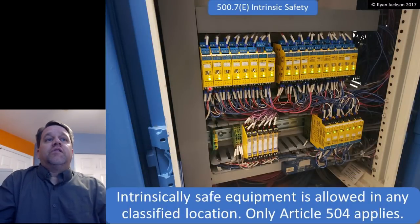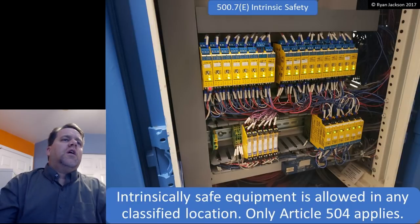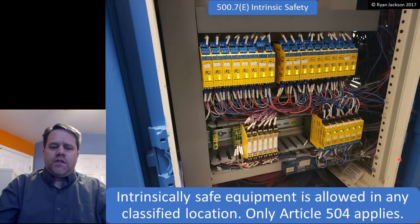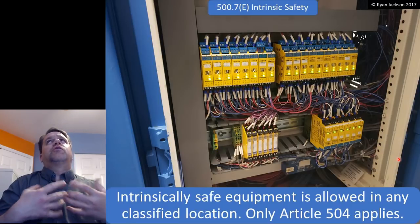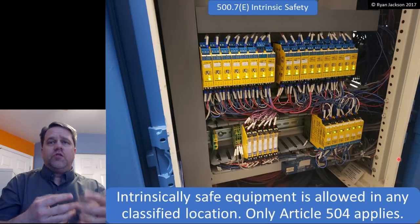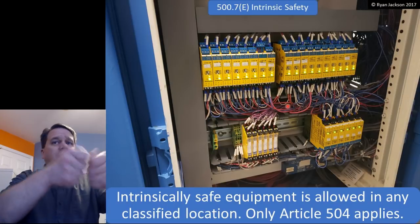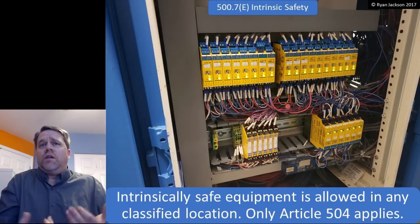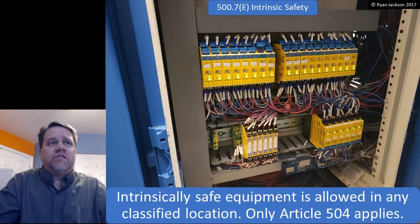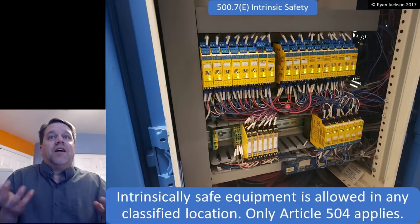We have intrinsic safety. Intrinsically safe equipment is allowed in any classified location, and only Article 504 applies. So intrinsically safe equipment is basically a circuit that cannot ignite the surrounding environment. There's not enough voltage and current to create enough energy to ignite the surrounding atmosphere. You take these conductors from the intrinsically safe system and bang them together, and you cannot create an arc, right? Not enough arc to ignite the surrounding environment. So an intrinsically safe system is allowed anywhere because you can't blow anything up. It's not a source of ignition.